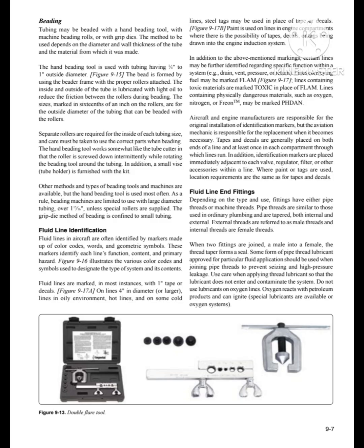And the fluid line end fittings. Depending on the type and use, fittings have either pipe threads or machine threads. Pipe threads are similar to those used in ordinary plumbing and are tapered both internal and external. External threads are referred to as male threads, and internal threads are female threads. As shown in this figure, double flare tools are shown below on the page.